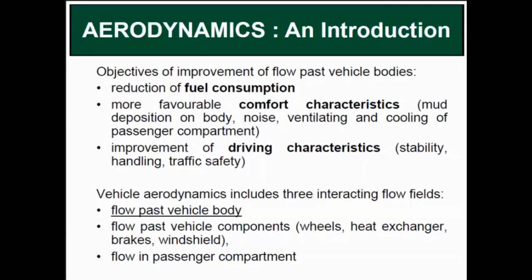Okay, in vehicle aerodynamics, you need to study the flow in three sections or three areas. First is flow past the vehicle body. Secondly, flow past the vehicle components such as wheels, heat exchanger, brakes, and windshield. And also inside the vehicle, flow within the passenger compartment. Normally this one studies the air conditioning inside the vehicle.